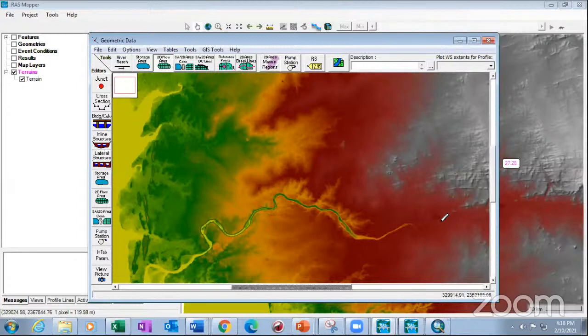It's kind of slow. Okay, and then I'll start tracing my area. This should be exactly perpendicular to your cross section. So wherever I'm drawing the line, it should be exactly perpendicular to the cross sectional area of the river. I'll create a couple of close points where I can see exactly perpendicular cross sections. Then I'll simply trace. See, in the beginning, at the upper boundary condition when you define it, there wouldn't be that much flow, so I can keep the lines close within the flow area. Likewise, I can trace.